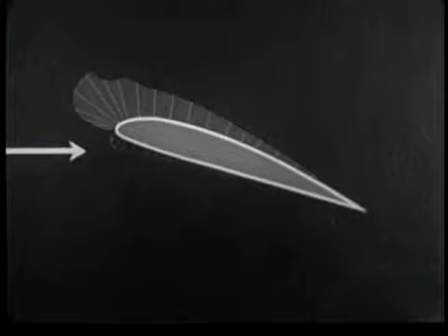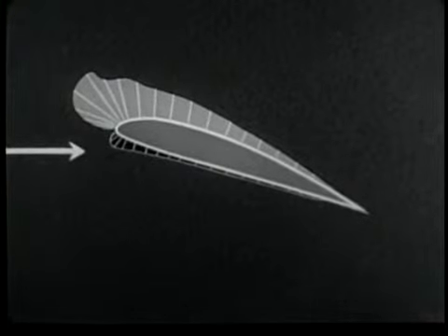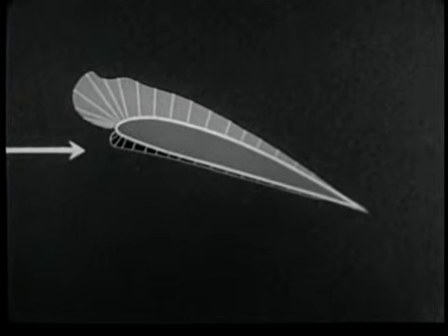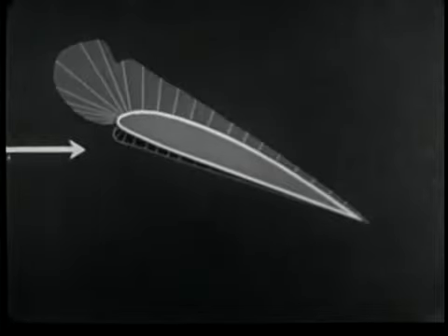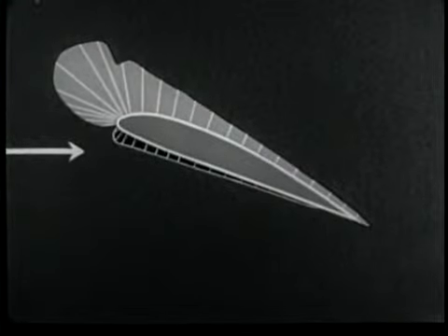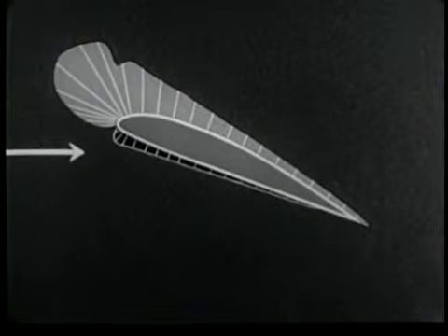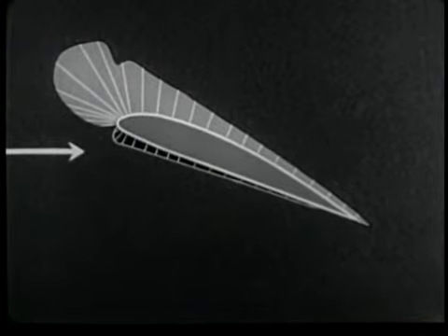By further increasing the angle of attack, positive pressures remain practically unchanged in both value and distribution, but the value of negative pressure continues to increase. At this angle of attack, the wing is well past its stalling angle, yet the positive pressures show little indication of change. With the negative pressures, the greatest change is noticed at the leading edge of the wing, where the area continues to expand, and the outline of the pressure area is extremely irregular.